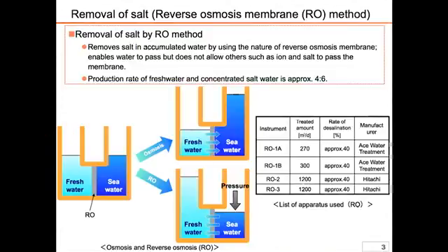The fresh water penetrates to the seawater side till the density of salt in the seawater side reaches a certain level. Meanwhile, it is the RO membrane's job to reverse the above function. To reverse the function, the mechanism is that of pressing the seawater side to transfer only fresh water to the left side, the freshwater side.